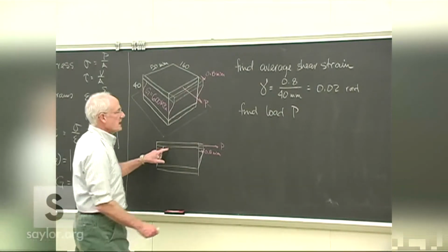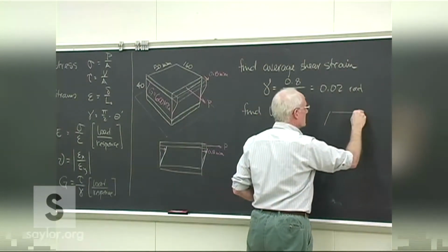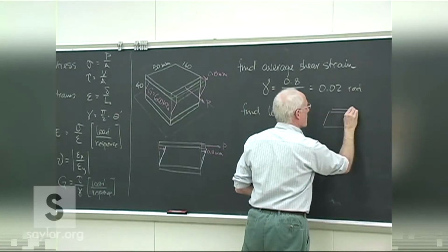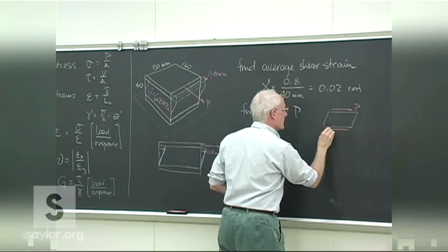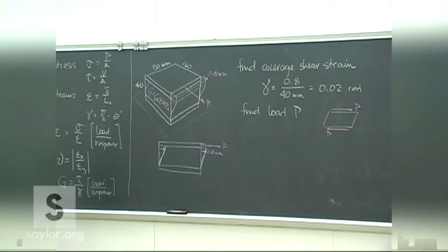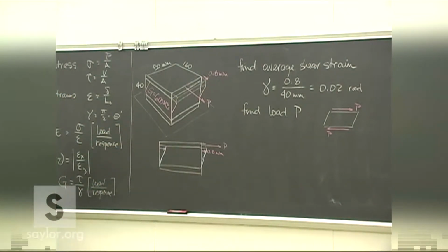It's the load P that's causing the shear. It must be balanced on the other side for static equilibrium. There's also obviously other things going on to resist the moment that those cause, the couple. But that's the mounting of it to rigid plates that will supply that. We're not looking at that in particular.